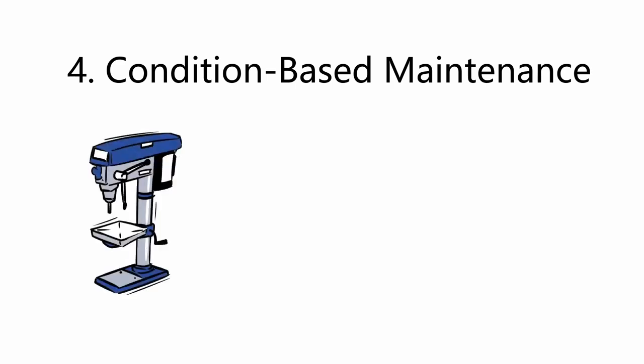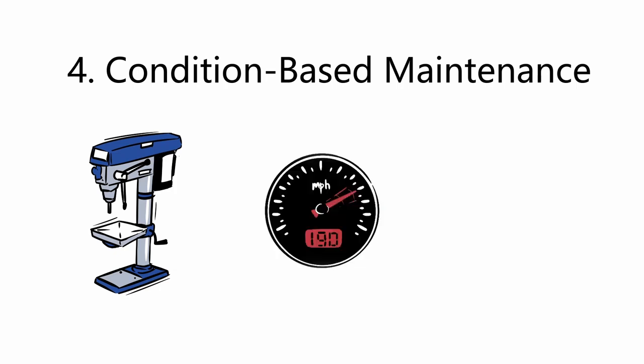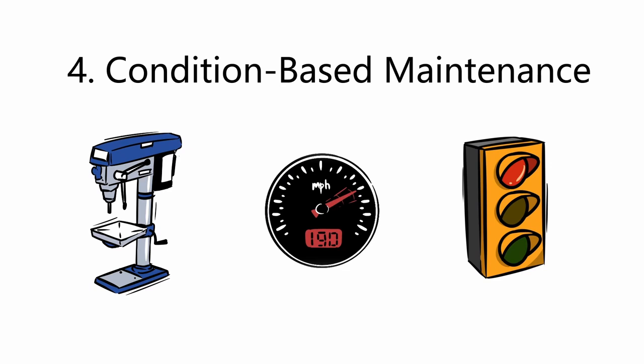4. Condition-based maintenance. Maintenance based on the equipment performance monitoring and the control of the corrective actions taken as a result. The real actual equipment condition is continuously assessed by the online detection of significant working device parameters and their automatic comparison with average values and performance. Maintenance is carried out when certain indicators give the signaling that the equipment is deteriorating and the failure probability is increasing.